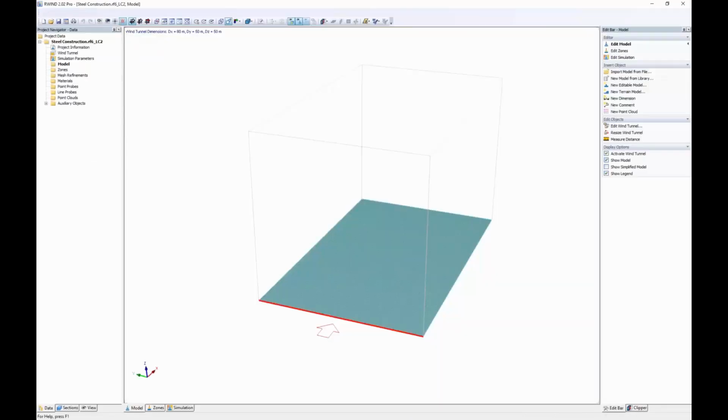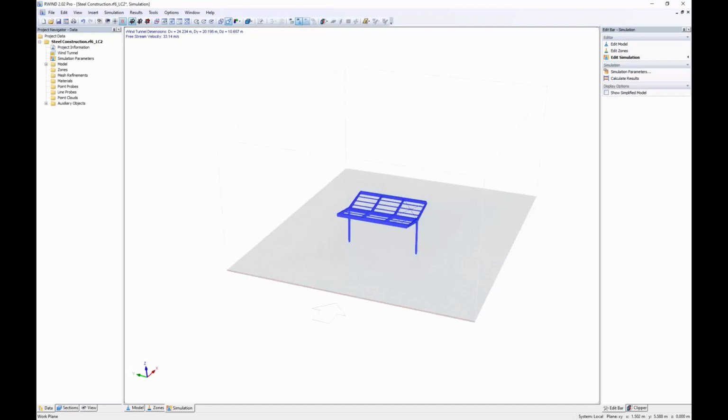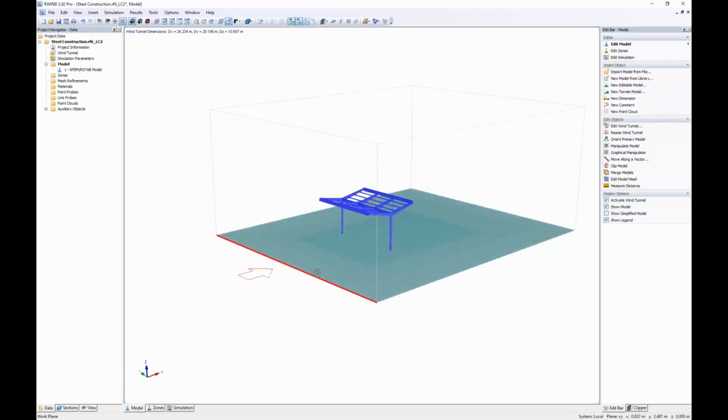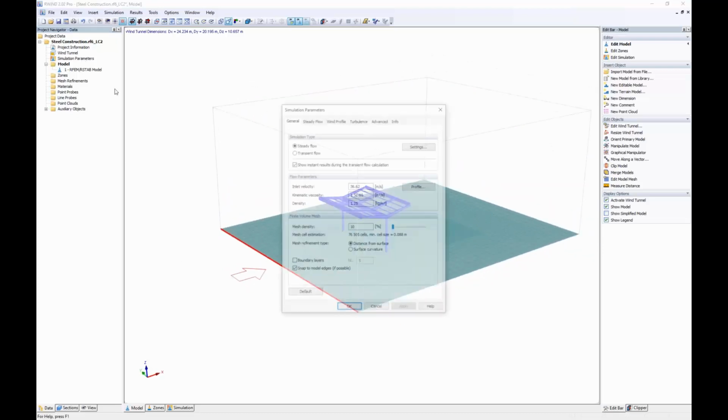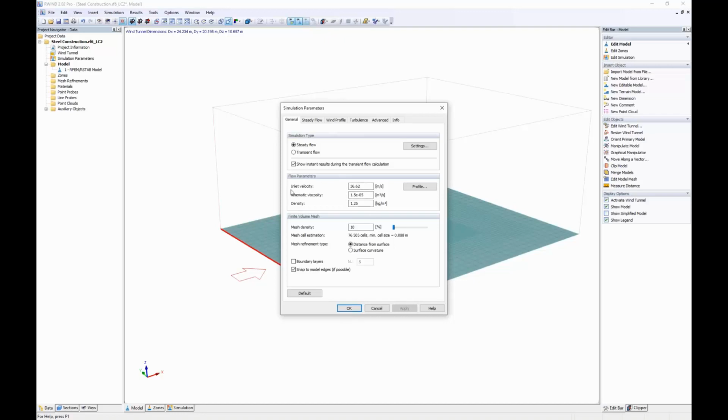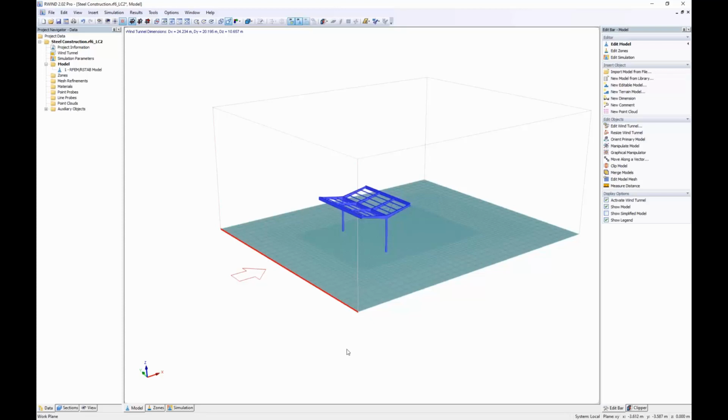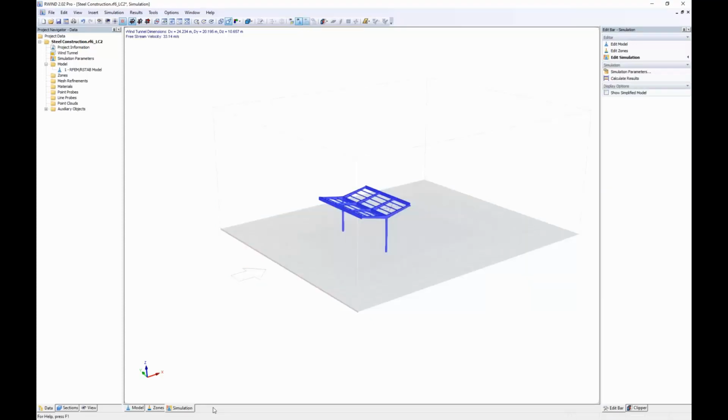Let's open this. And you see here we have, let's say, our wind tunnel with terra, with model, entrance, with all properties, so steady flow, flow parameters, all calculation parameters, all this stuff is defined here, and yeah, we can start calculation. So I do this, start calculation. This is maybe what is behind. So if you press calculate in RFEM, the program will move this model like this here in the wind tunnel and will press the button calculate.